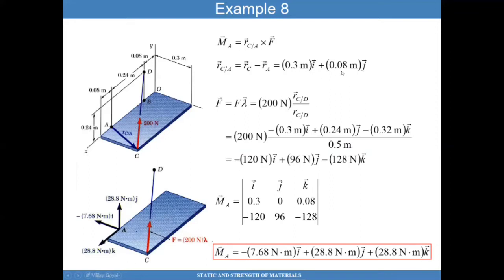I encourage you to examine the error there, because clearly the position vector AC is in the z-x plane. Therefore, I should not have any components in j hat. It should have been k hat. So that's a mistake here, but it's great that we have a mistake, because you can see how to quickly correct it. Okay, so that's the moment that we find for this problem.